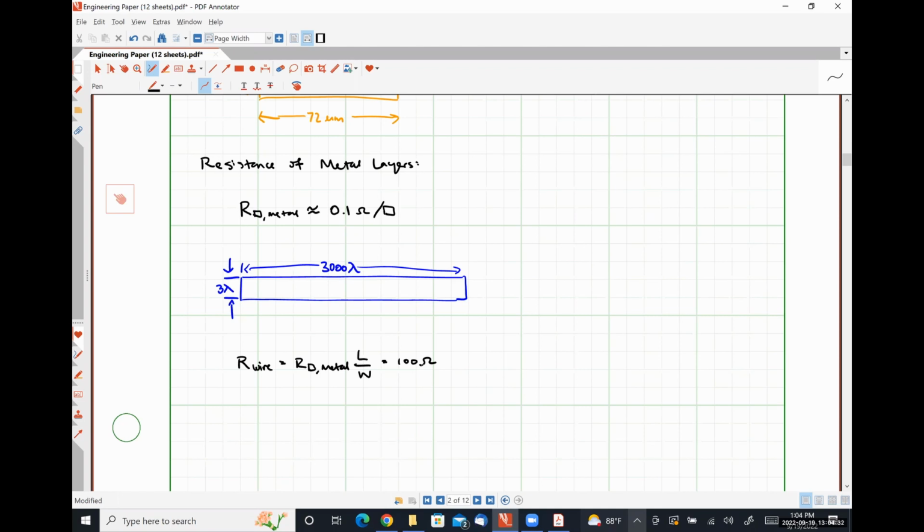So let's look at what the capacitance of this wire is going to look like, where this is from the metal 1 layer to the substrate, okay? We're actually going to have to use both the bottom section of this table and the top section of the table. In our poly to poly 2 capacitor, we only had to use the top section because there wasn't data provided for the specific thing that we're looking at here.